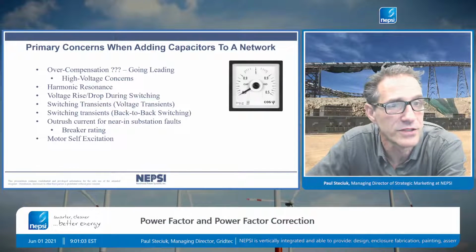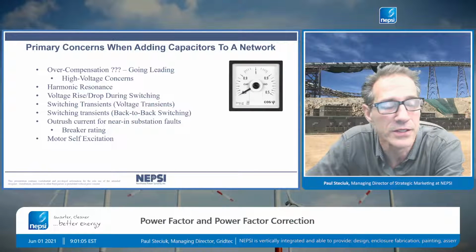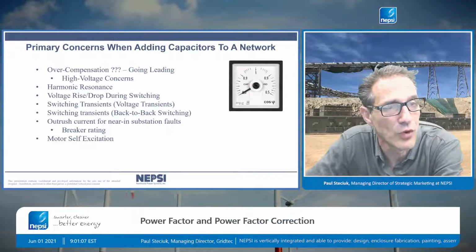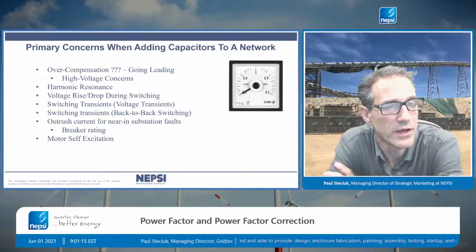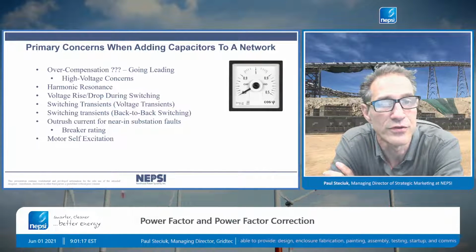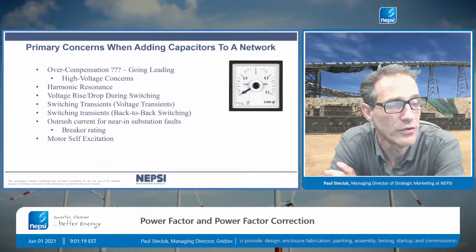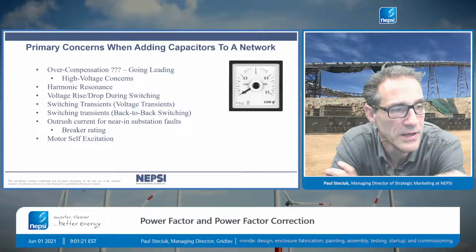There is technology out there, point-on wave switching, often called zero voltage closing, and then you have pre-insertion resistor technology. All those look to mitigate switching transients.